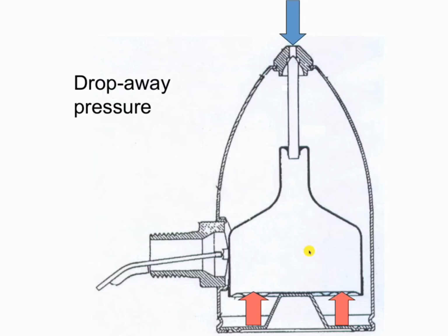Because when you talk about steam being at a constant pressure, these things have pressure controls. I've been inside of these buildings, and there's always something to actually regulate the pressure or hold it or cut it out, so that way you don't have an excessive buildup of pressure. Now, when you're dealing with Con Edison steam, you can run that at even lower steam pressures, because why? You're not dealing with a boiler that has to do a pre-purge and post-purge cycle. So you don't have to worry about having a drop of pressure. You can pretty much keep it almost consistent.